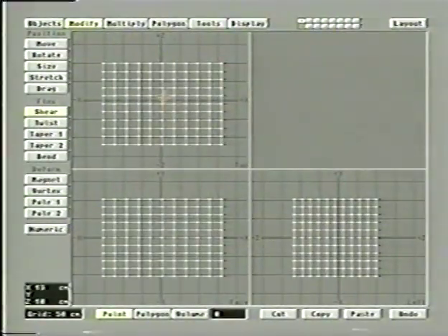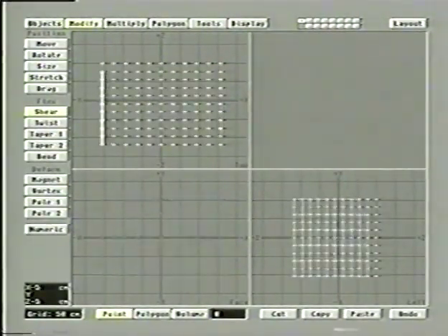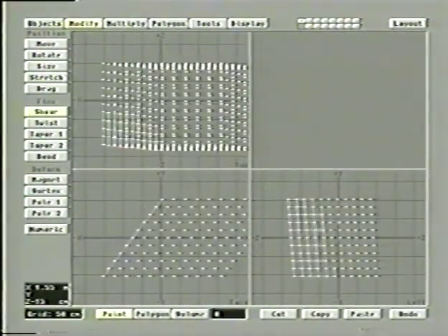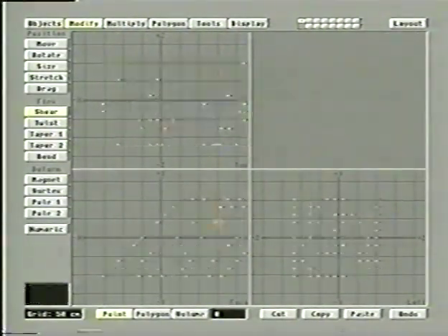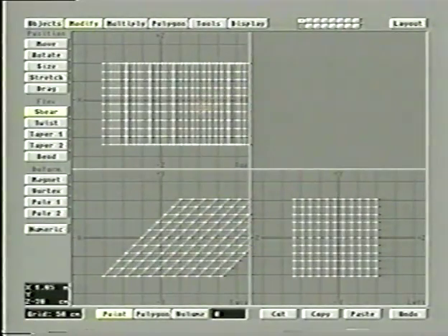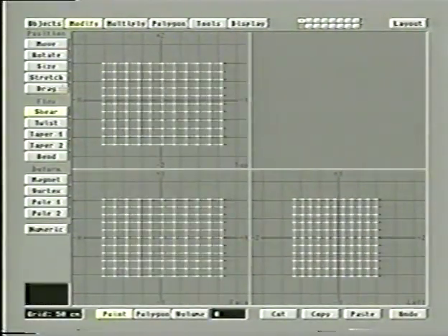And let me just show you how that functions. We'll just go to Shear, click up here, hold down the mouse and drag. And you notice it's doing a move, but it's only moving the top. It's only moving near where I click down. Now, the way we can change that, if we want to move the bottom instead, let's just undo that, is go to the numeric options. Remember, N is the keyboard shortcut for numeric.